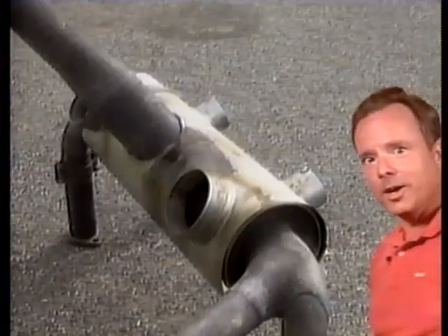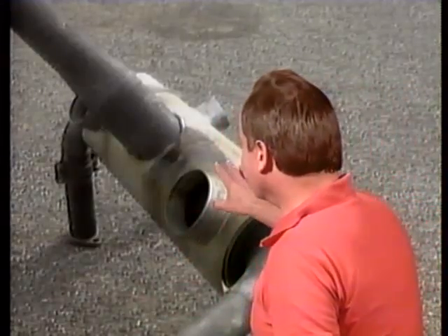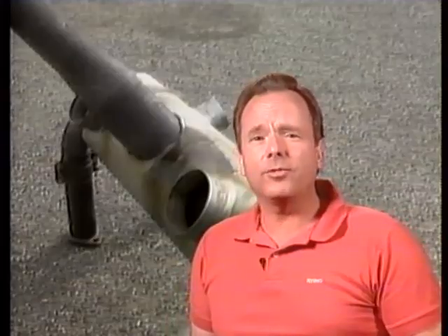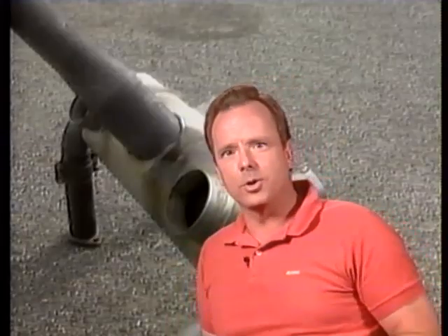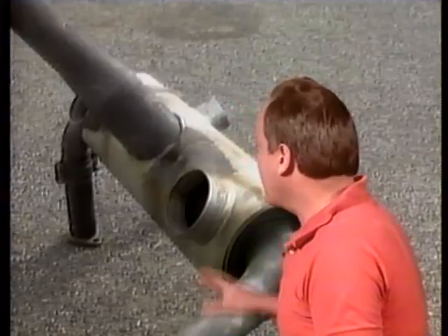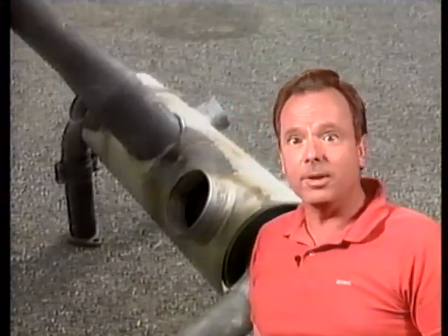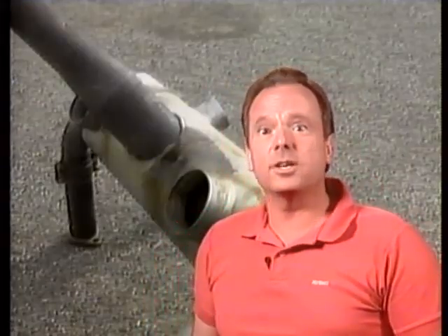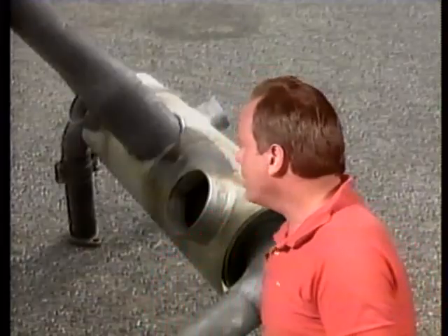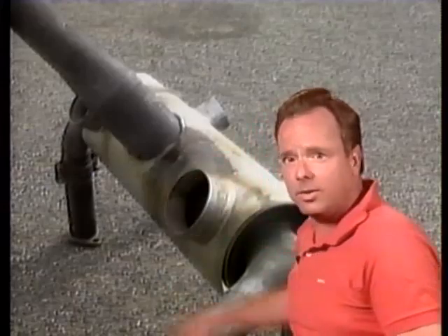So as a mechanic, what are you going to do about all this? Well, you're going to inspect the exhaust system. That's what you're going to do. It's not the way they're going to ask you questions on the FAA written exam. Let's talk about the way they're going to ask you questions about this on the FAA written exam. Here's one. The exhaust system on aircraft using a jacket around the engine exhaust as a source of heat should be visually inspected frequently. And operational carbon monoxide detection tests should be performed periodically. They're saying check for carbon monoxide gas inside the cockpit. Here's another one. An aircraft that utilizes an exhaust heat exchanger as a source of cabin heat should have the exhaust system inspected with the heater air shroud removed.